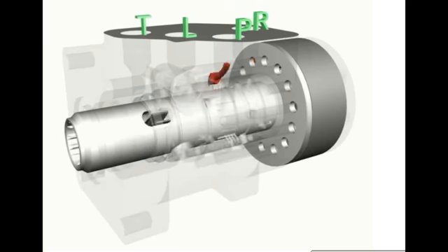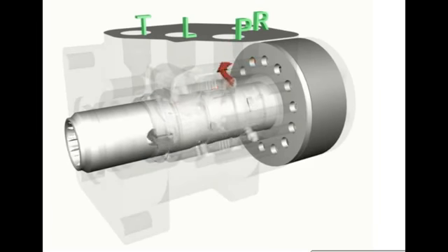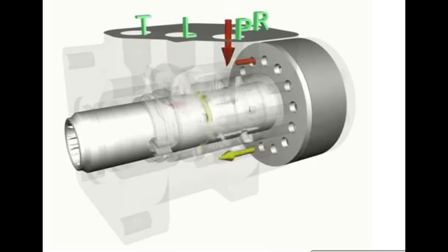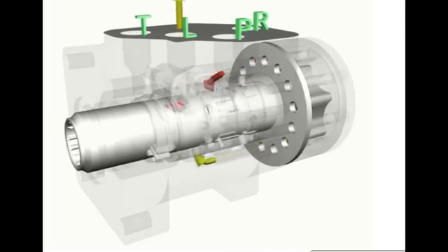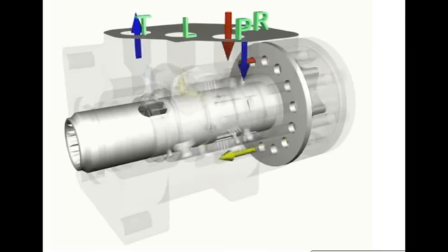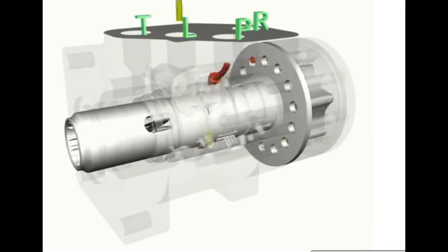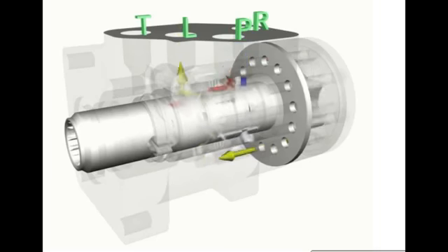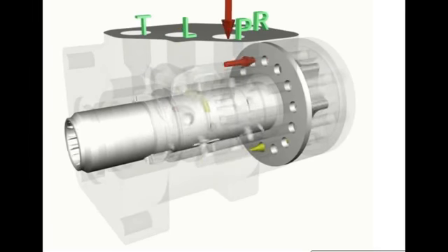Flow is metered through the gerotor section of the steering unit, equal to the displacement of the gerotor and the rotational speed of the steering wheel. The fluid flow is ported to the open side of the gerotor and metered to the closed side as the gerotor rotates, and flow passes out through the L port of the steering unit.